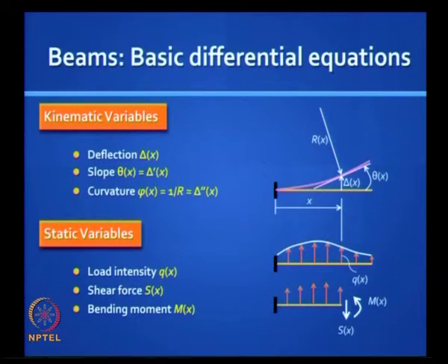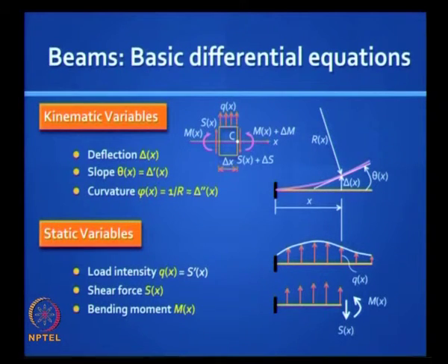Okay, so that is important to note. So that is Q of x, the derivative. So how is it related? What is the relationship? What are the basic differential equations that relate these three quantities? Shear force is the derivative of, okay, so you can prove this by taking a small element of the beam and just applying direct equilibrium, and you can prove that the load intensity is equal to the derivative of the shear force. The shear force is the derivative of the bending moment,